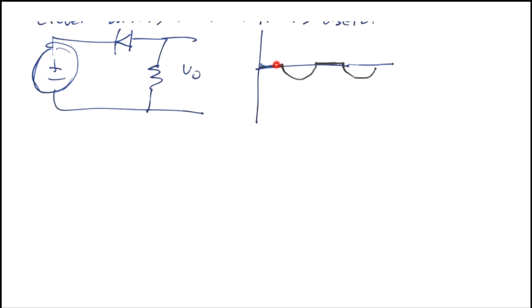So the regulator, or the rectifier we looked at first, picked up the positive going peaks, but if we put the diode facing the other way, then we'll get the negative going peaks, right? And so we'll have a signal which is only negative, and we'll have a signal which is only positive, the positive peaks being here, right? And the negative peaks being here and here.